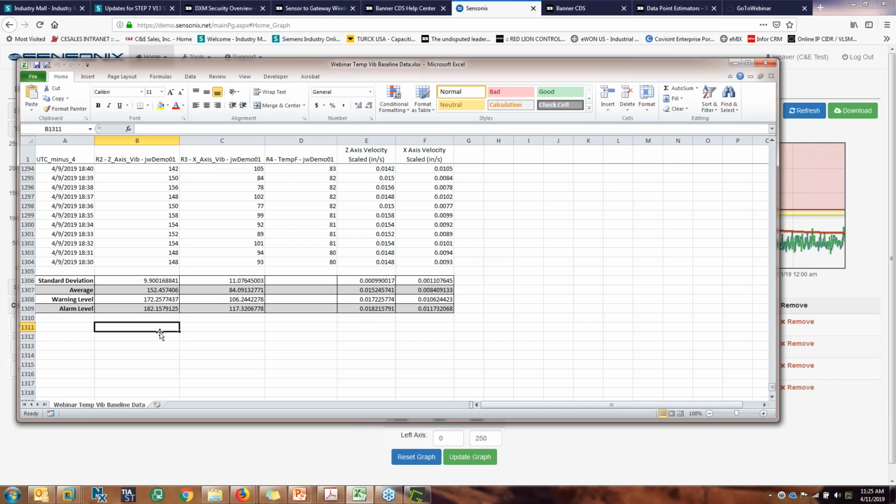So if I get specifically 5 consecutive readings, now normally we're not reading every 5 seconds like I am, we're going to read more like every 5-10 minutes or even longer, which is more than adequate when we're analyzing a motor over its life. So we're going to look at the baseline data. If I've seen 5 consecutive readings at the warning level, 2 standard deviations away, then I'm going to annunciate a warning. 3 standard deviations away is when I know the motor's actually getting close to its end of life, and it's close to a critical stage.